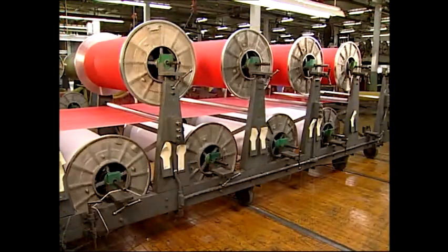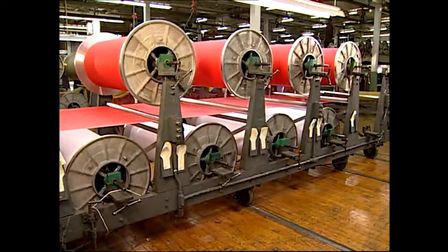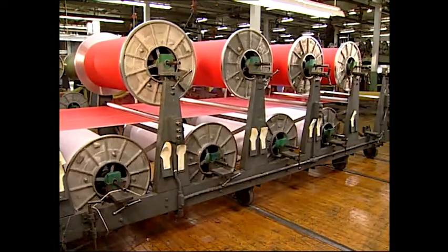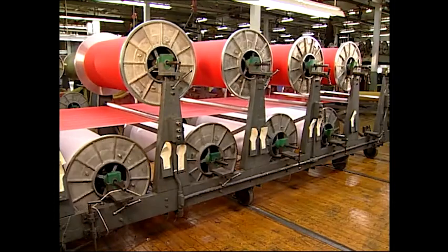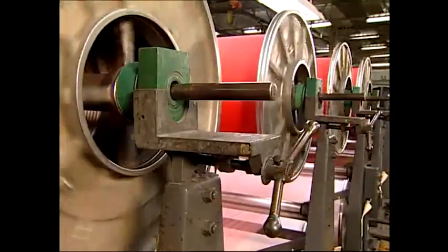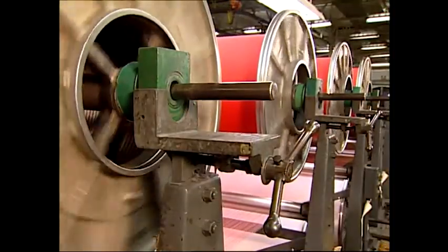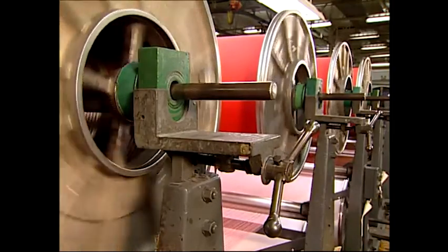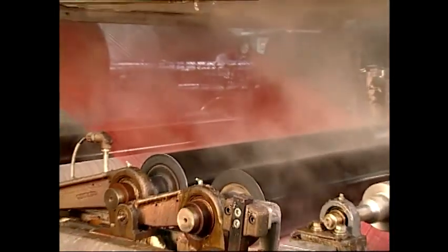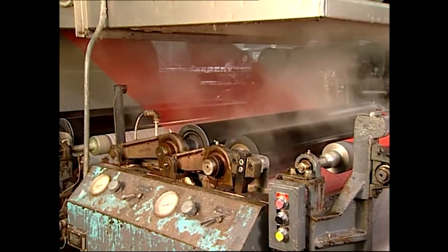The section or die beams are placed into a slasher creel or slasher magazine, where the ends from each beam are added together so they can be sized and wound onto a single loom beam. Once assembled on a loom beam, some yarns such as plied and filament can weave without additional processing. But most yarns require a sizing with chemistry to improve the weaving performance of the yarn. This process is called slashing.